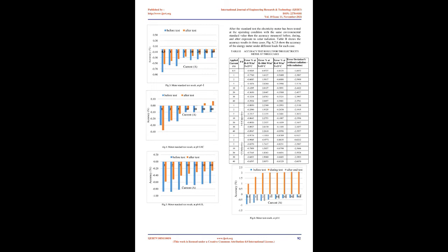In addition, a method differing from the standard method was used to study the solar effect on the meter at normal operation. The energy meter was supplied by its nominal voltage and variable balanced load current, using a comparator reference standard watt meter and energy meter manufactured by Zera, model COM303. In the lab, the meter's error was measured and recorded to know the extent of the radiation effect on the meter under different loads. The electricity meter was tested at the operating condition and 23 degrees Celsius before exposure to solar radiation as a reference condition.